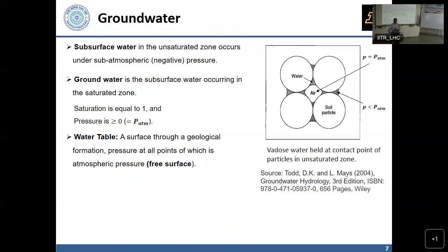The total head, or the energy status of water anywhere, we typically use piezometric head. So pressure head plus elevation head. Velocities in groundwater tend to be much smaller, so the v square over 2g, the velocity head, is rarely a factor in the total head.